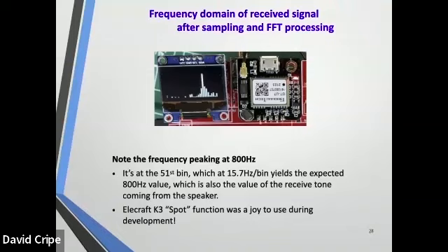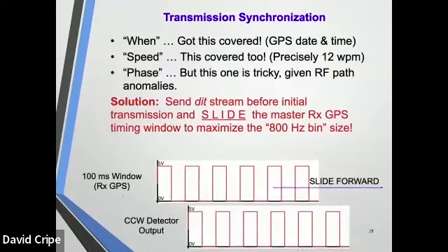And just another indication, you all have probably seen some kind of applications that show the spectrum of an audio signal. So you feed an audio tone, 800 hertz, in, and with some test software that I've got going on my system, we were able to see a tone pop up right at 800 at bin 51, which indicates 800 hertz. So another indication that things are kind of working properly. And also note the tight SD, standard deviation, on that. The signal is really quite evident there.